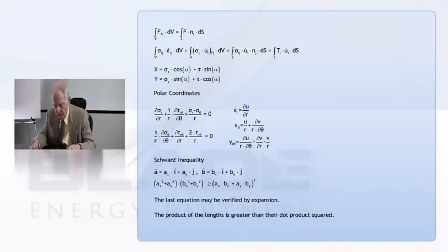If you paid a lot of attention in thermodynamics, that begins to sound a lot like the first law. And the difference is that in the first law, you would have to say what happens on the left-hand side. In the case of plasticity, you'd say, well, some of that gets stored as strain energy, that's the elastic part, and some of it gets dissipated probably as heat, or the temperature of the body goes up.